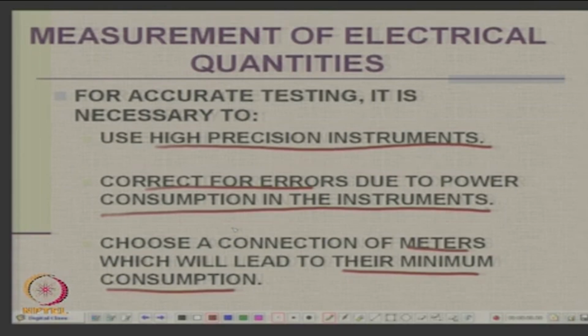And how do you know that your meters are accurate? It's specified, your meters must be say 0.1% accuracy, 0.5% accuracy. But how do you know? It is written, so many things are written. Pardon? We have to get them calibrated. How? From standard institutes.